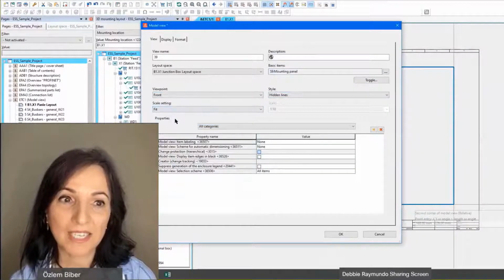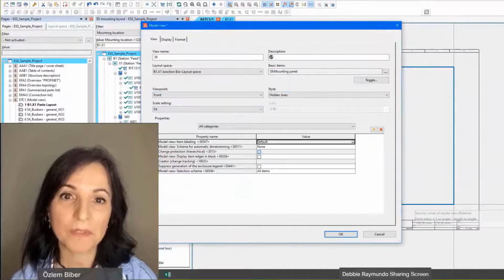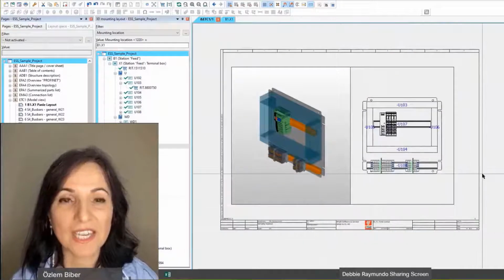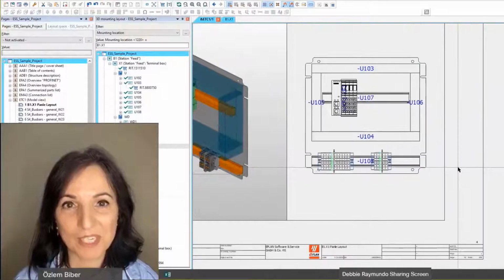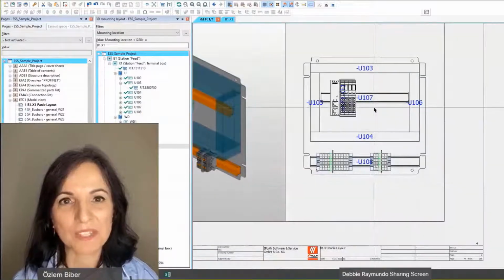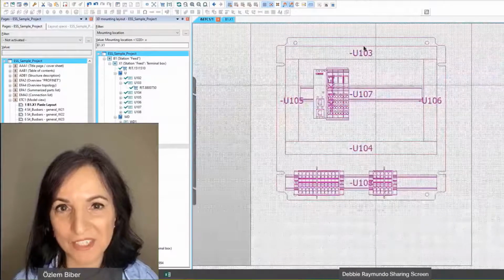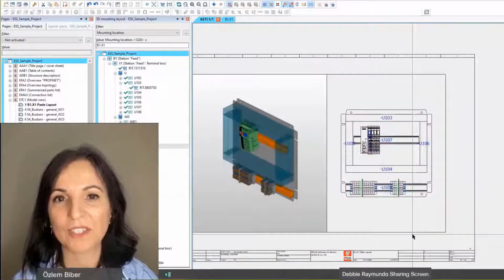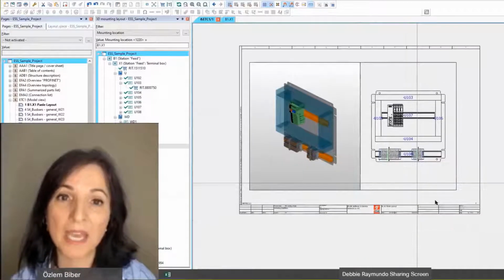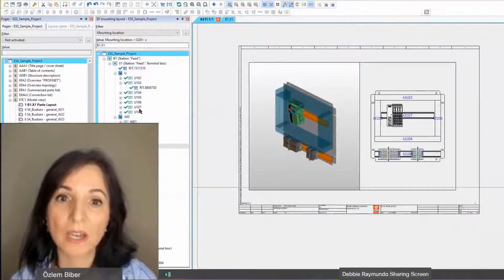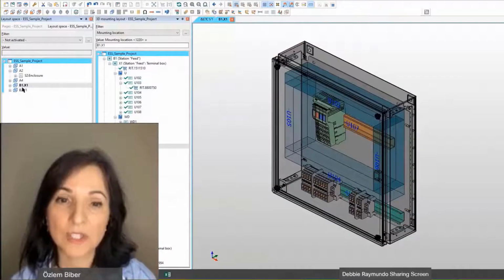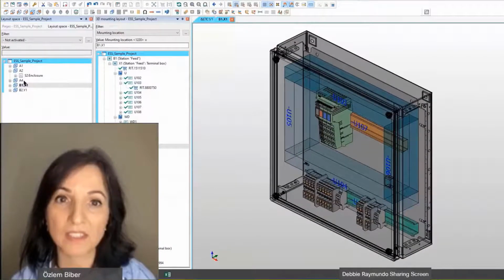It can all be printed out for them in a report format, but for more automated processes, they can export all this wire fabrication information out of Eplan into their wire fabrication equipment. So they don't have to manually enter this information, and certainly don't have to look through schematics. So these are, I think, the couple of trends that we're seeing, and panel builders really should look into more about it and consider it to stay competitive, in terms of saving time and cost in the panel shop.